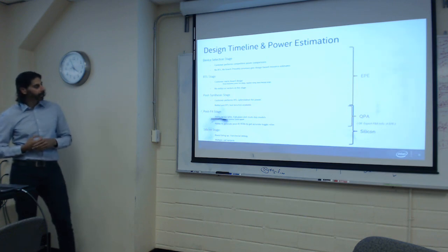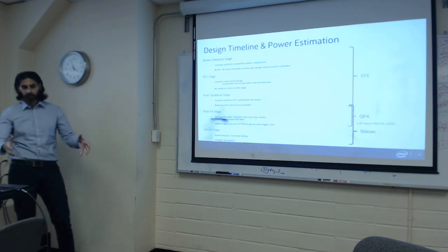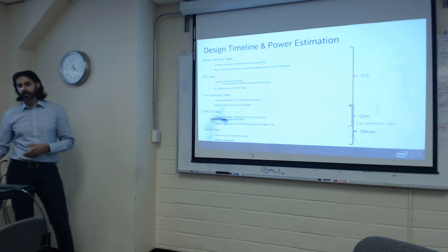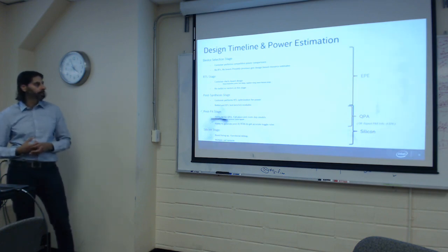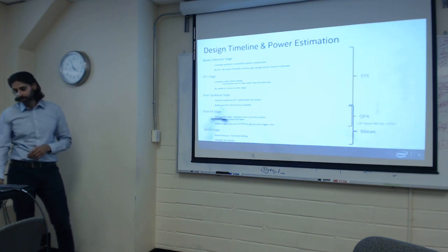And finally, once you get to silicon, customers can continue to use our tool, or they can actually get a power estimate from their actual silicon setup. And oftentimes with FPGA design, users don't just have one programming file that is their end system. They have multiple variants testing in parallel, and so oftentimes they find you just program on board and get a power estimation exactly at that stage. So this is kind of the life cycle of a typical FPGA design.